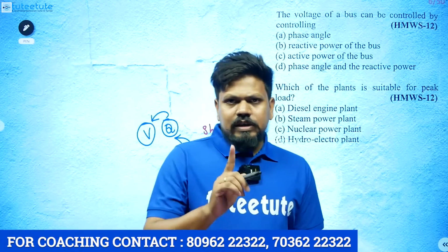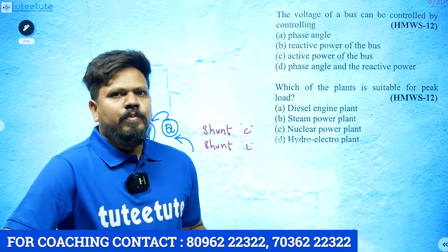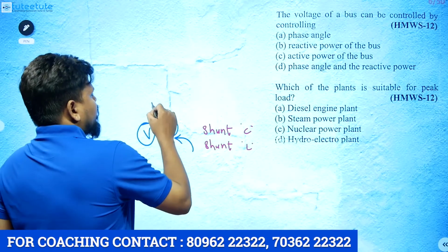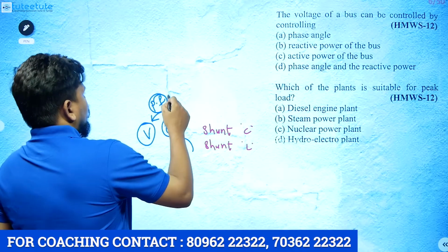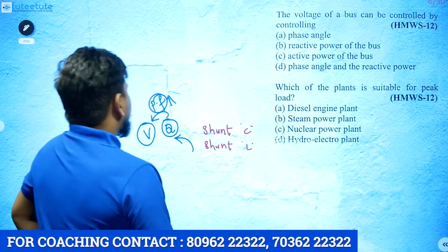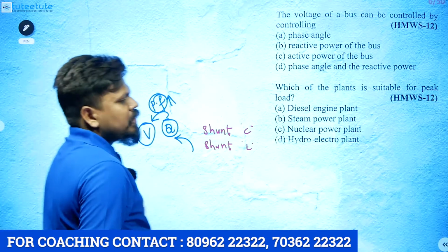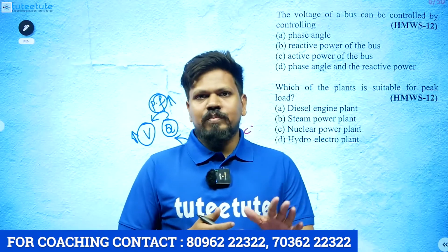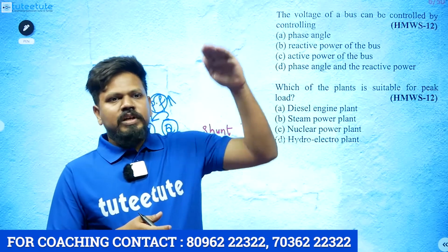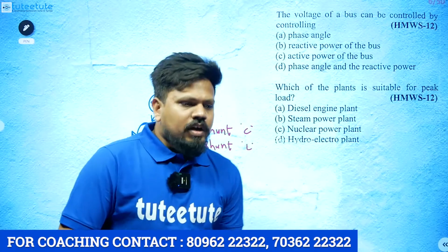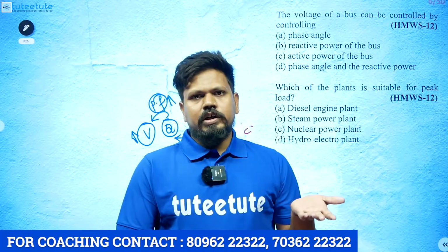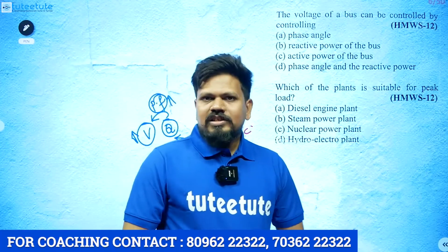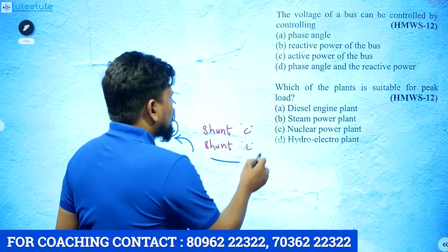That's it. So whenever you control or compensate the reactive power, automatically the power factor will improve first, and similarly the voltage profile will also improve. Improve means the voltage is not simply increasing. Remember, if you are getting over voltage, it will become normal voltage. If you are getting under voltage, it will become normal voltage. According to that we have to use a shunt capacitor and shunt reactor. In some other example I will explain these things in detail.